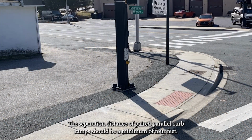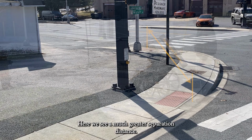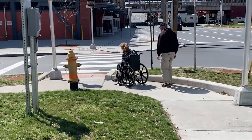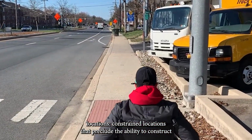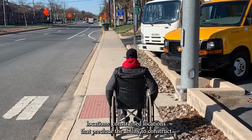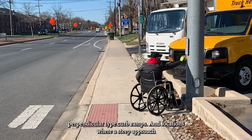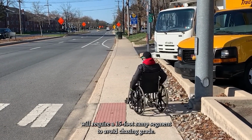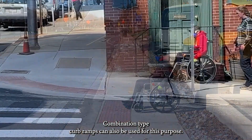The separation distance of paired parallel curb ramps should be a minimum of 4 feet. Here we see a much greater separation distance. The department prefers the use of perpendicular type curb ramps. However, parallel curb ramps are the preferred treatment at the following locations: constrained locations that preclude the ability to construct perpendicular type curb ramps, and locations where a steep approach will require a 15-foot ramp segment to avoid chasing grade. Combination type curb ramps can also be used for this purpose.